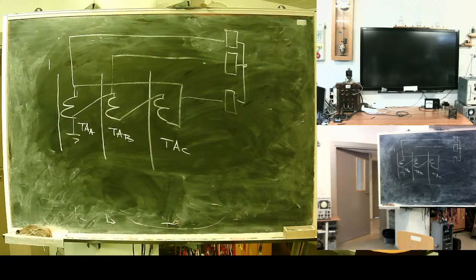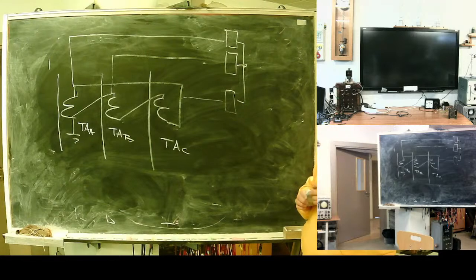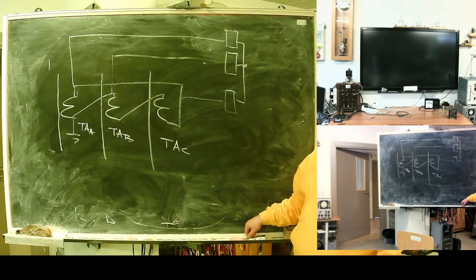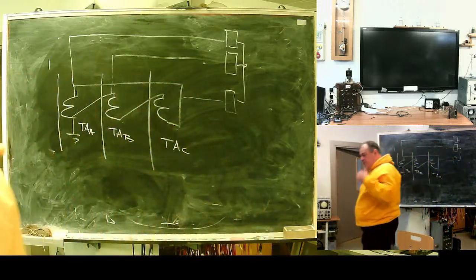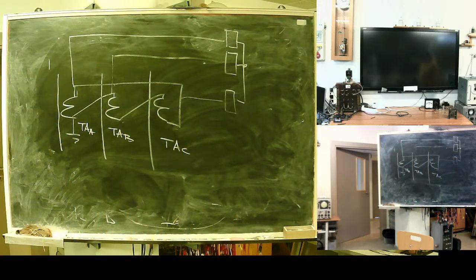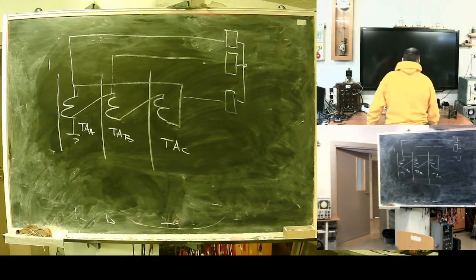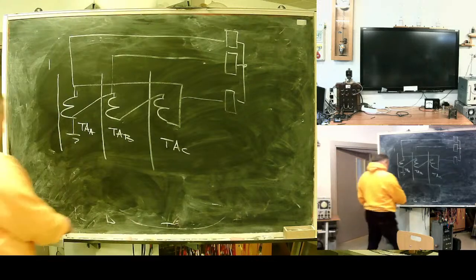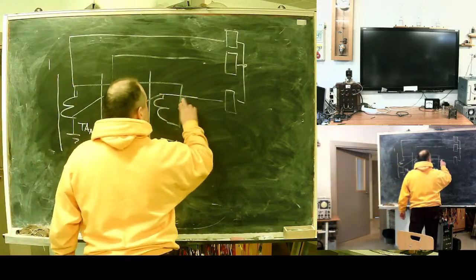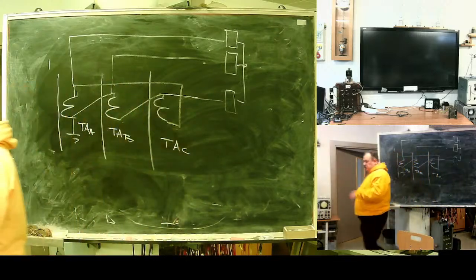First, it has schematics factor square root of 3, and this schematics is immune to ground fault. This thing will never trip at ground fault. It appears to be strange, and why should I use it? Immune to ground fault. This kind of connection for overcurrent protection would be a, I see an error. This should go here. For overcurrent protection it's quite strange.